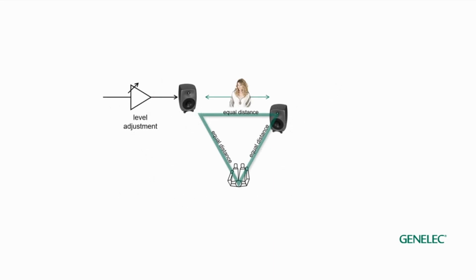Let's look at the case where two monitors have different delay for audio to reach the listening position. We don't know the reason for this, but it is not very untypical to have this kind of problem in a stereo system or in a multi-channel system. The delay difference will move audio images, and this will have an influence on the mixing work. Actually, less than 1 millisecond of delay difference will entirely pan audio into the nearest monitor. If you think of the distance difference, it's not a huge distance. 1 millisecond is about 340 millimeters or 13.5 inches.